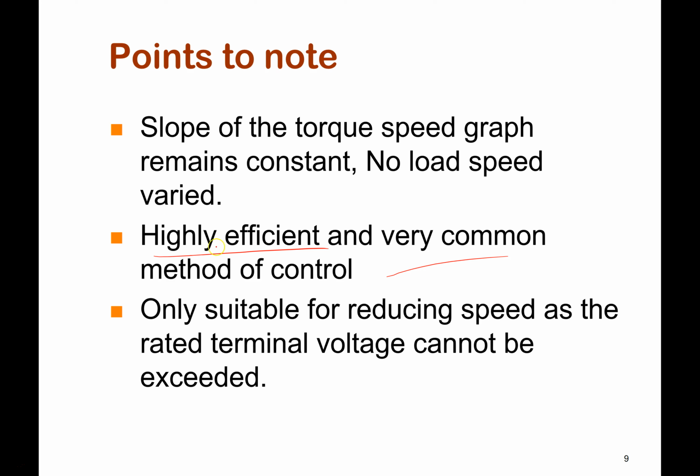But again, you could only reduce the speed. You can't increase the speed from the rated speed, because that would mean you'd have to go beyond the voltage ratings, which is what we don't want to do. And lastly, we have flux control.